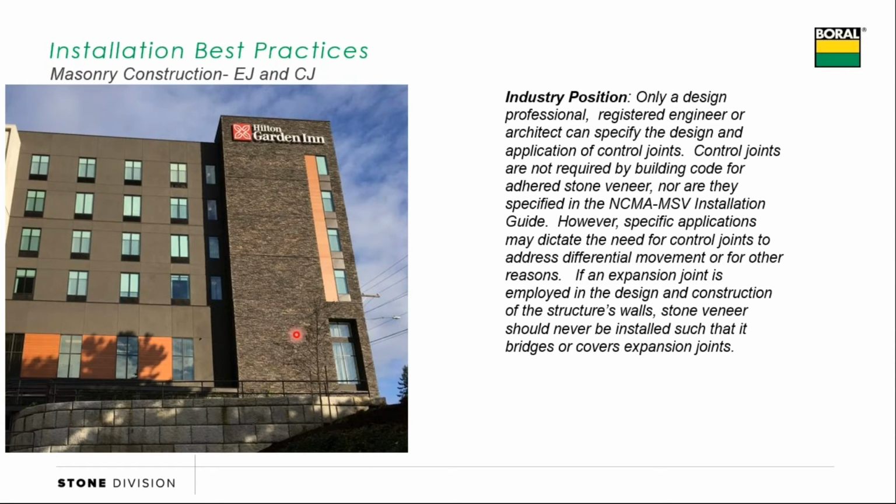In this case, this was a wood frame building going up 4 or 5 stories tall. That is probably some 2x4s and sheathing that's fairly green, wet. And then we hang our stone with an extra 17 or 20 or up to 25 pounds per square foot of additional weight on that wall system. Now, what's going to happen over the next 6 months to a year as that wood begins to dry out? Well, it's going to dry out. That means it's going to shrink, and there's potential for that building to compress. It could lose a half an inch or more over that time.